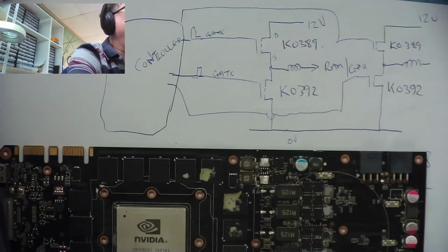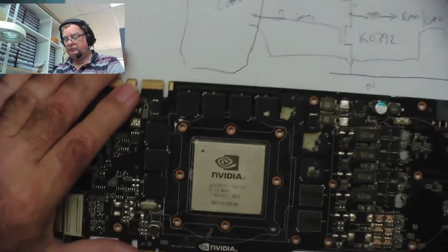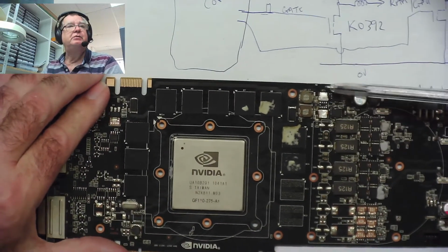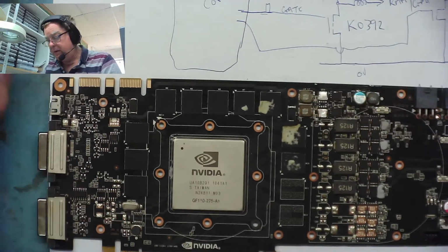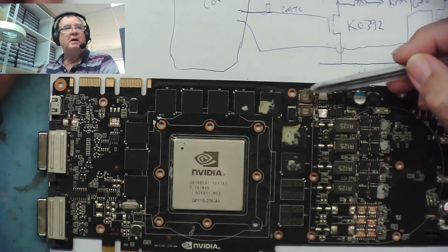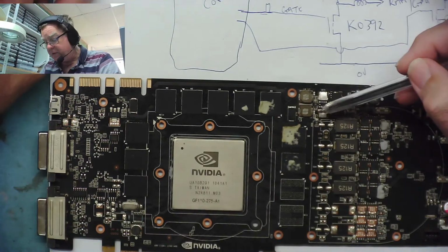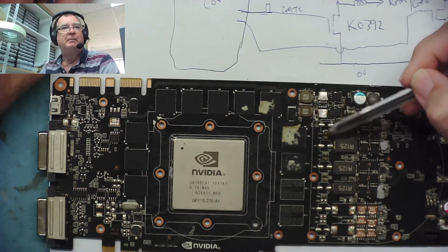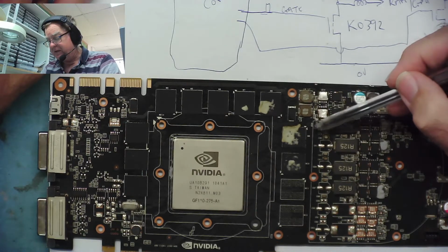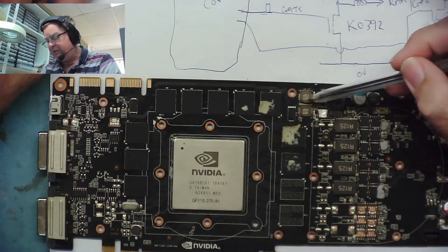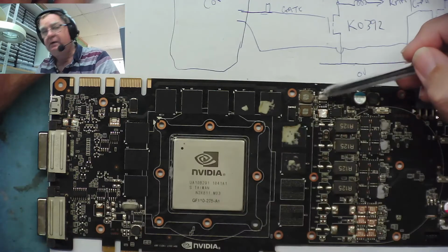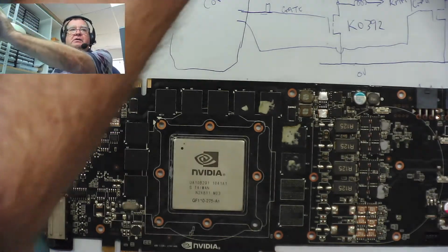Let's go back and have a look at the unit. So I'm going to take these two coils out. It takes quite a bit of heat to do this, but it's fairly easy to do. But this time I am going to put a bit of Kapton tape around these resistors here, because I will need to get a lot of heat into here, and there's some very small components here. You can see them on the...